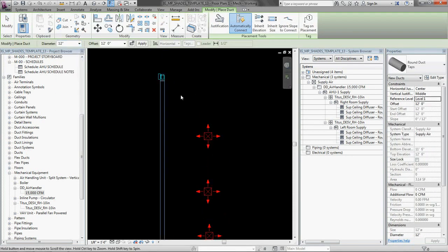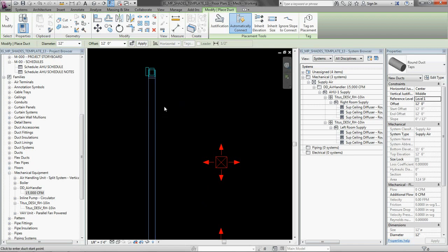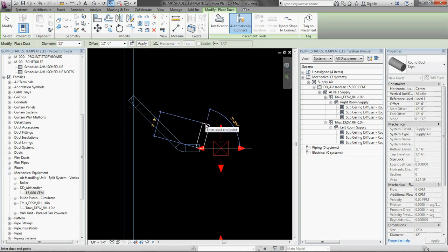And something about modeling duct here is that a typical workflow before Revit would be to size the duct with a ductilator, say, and draw the duct the size you want it to be. Now you don't have to do that. Just draw it ballpark. Don't think that much about it because you don't have to. I know that sounds bad, but just follow me here.